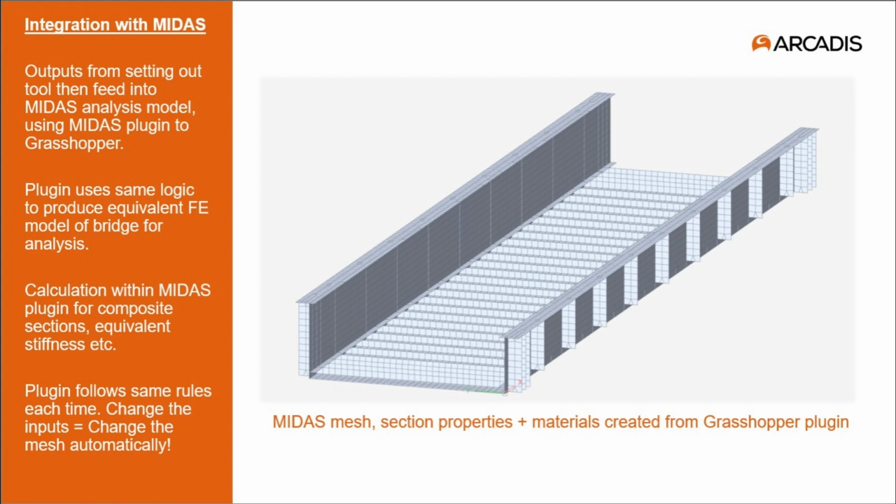So the second step in this process is to then link the 3D geometry of the concept design to a MIDAS analysis model. This is done using the plugin that MIDAS have developed to create a connection between the Grasshopper and MIDAS software programs.